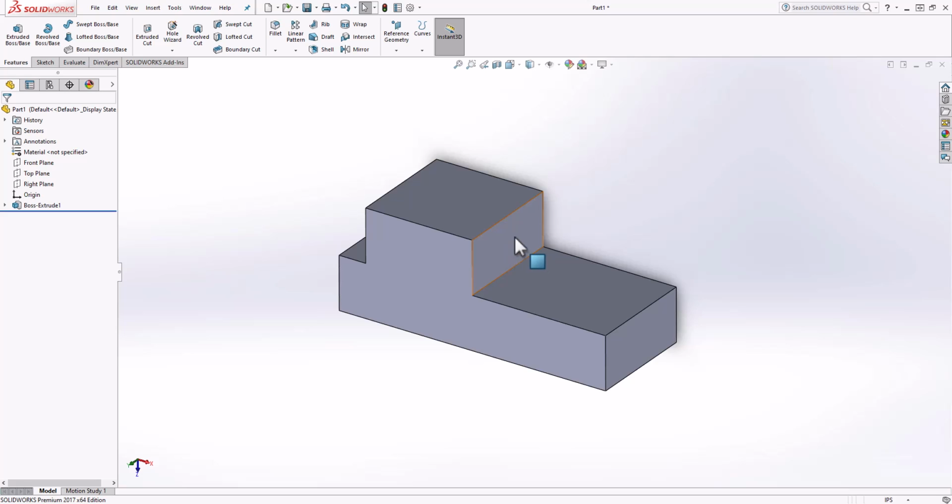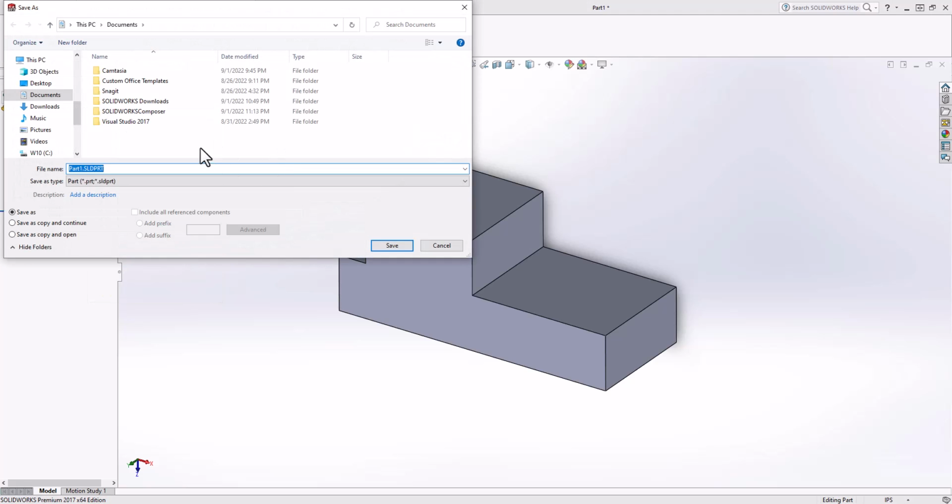I think I'm going to stop here. This is a good place to end. This would be how to create a part. And what I'll do is just say save as. So we'll say file and save as, and I want to give this a name. So I'm going to just make a working folder in documents called SOLIDWORKS Parts, right? Just something simple. And then this is going to be first part, okay? And you can add details here, but it's not necessary.